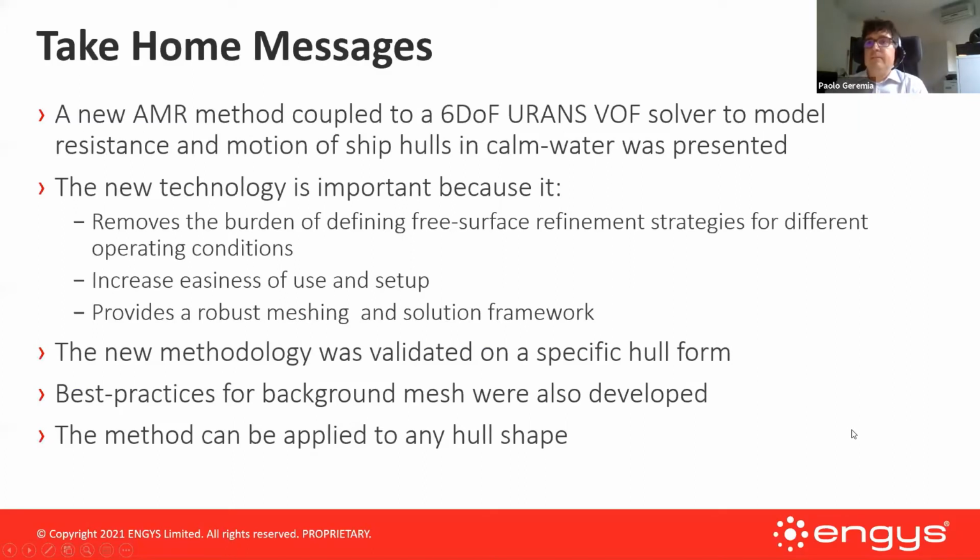Concluding, the method based on automatic adaptive mesh refinement, AMR, was coupled to a 6-DOF unsteady RANS VOF solver, which was applied to displacement hulls for the water resistance prediction and motion, using an OpenFOAM library.